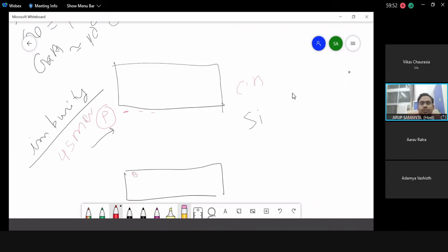So here, if you want to create an electron from the valence band, it needs 1.1 electron volt of energy. But if phosphorus is there, phosphorus has only an energy difference of 45 milli-electron volt below the conduction band. So this electron of the phosphorus can easily go to the conduction band, and the number of electrons in the conduction band should be higher at high temperature. So even at room temperature, as per your replacement of silicon by the impurity level, a number of electrons should be there in the conduction band. So you can increase this by giving an impurity which is close to the conduction band.